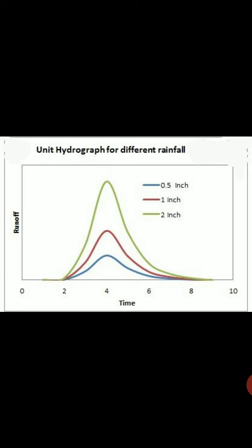Next point is divide the volume of direct runoff by the area of the drainage basin to obtain the equivalent depth of direct runoff.